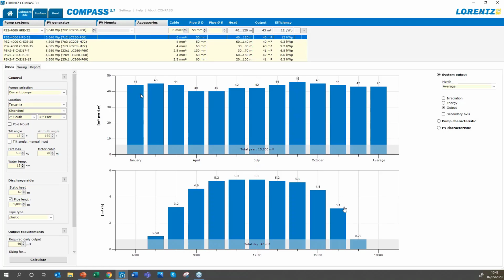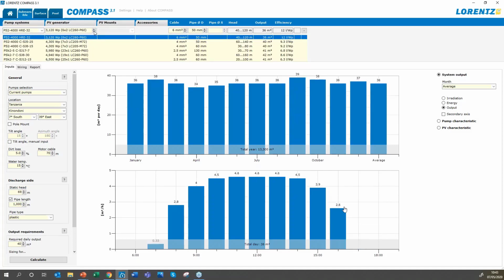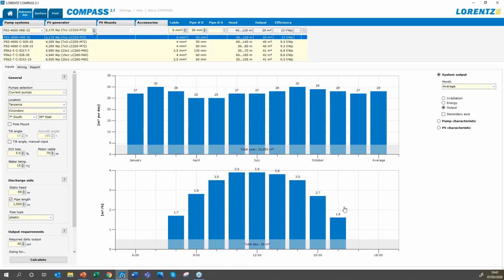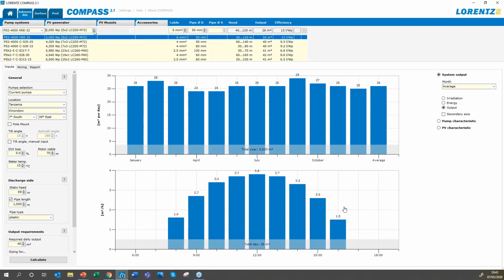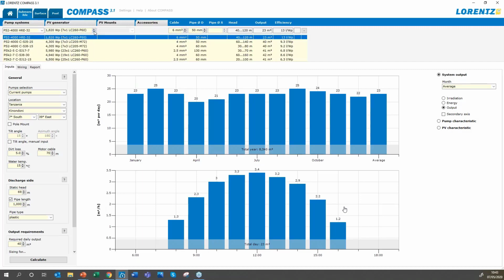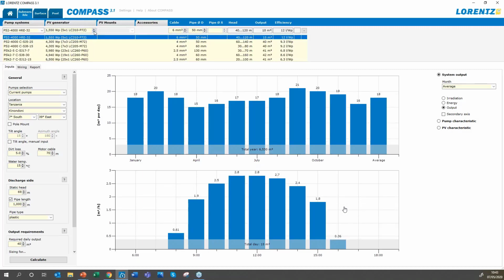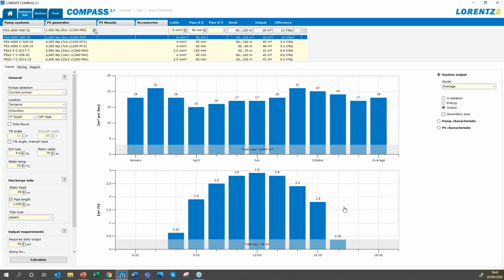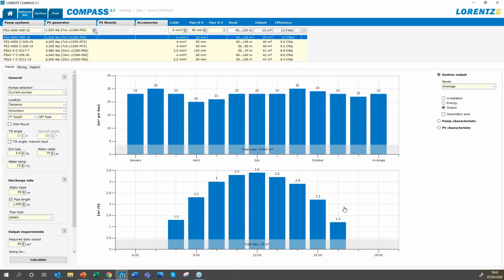So what we could do is, remember the customer saying this is in 18 months time, what we could do is sell this pump, but actually we can reduce the power on it so that it only delivers 20 cubic meters per day at the moment. Let's keep taking our power down. So that's just gone too low. Yeah, so that looks pretty good.